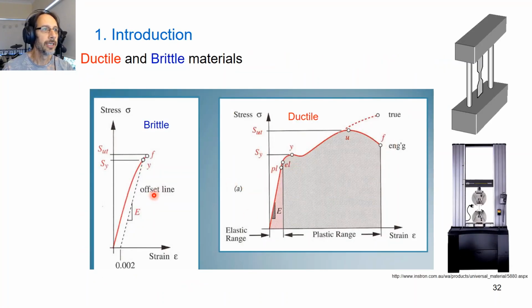All right, so what we have here are two charts of stress versus strain, or you could think of it in terms of load versus deflection of a material. So we do standard tensile or compression tests. These are results of tensile tests. We might use a machine something like this. This is a simplified representation up here. We would pull up on one or other of these blocks, or the crossheads as we call them. Here we have a base. Here the crosshead will move up or down, applying a tensile load to the specimen in here.